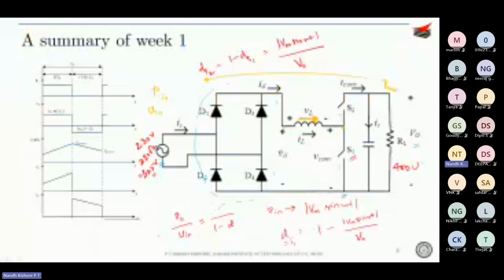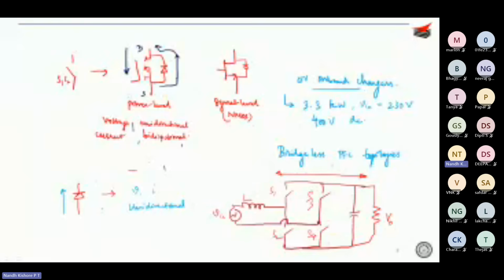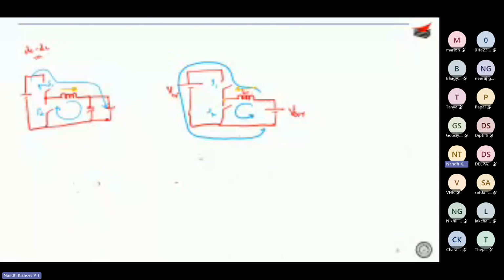Okay, so one person was asking about the regulated power supply. So the point is what generally people do is they use two-stage topologies. That is, I'm not drawing the entire converter once again, but the same converter, correct? That is you're having grid voltage over here. So you're having diode bridge rectifier DBR plus boost power factor correction based circuit. So what you get at the output is a regulated 400 volts. Let's assume that it's going to be 400 volts.